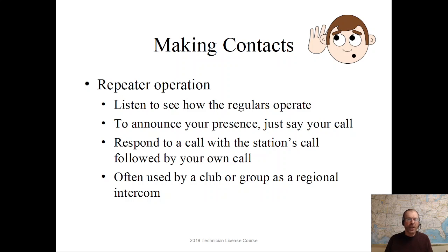Of course, if we intend to use the repeater right then and there, it's important to listen to see if it's in use already, because we don't want to barge in on somebody else's conversation. To announce your presence, just say your call. So, if I go on a repeater, I'm not going to call CQ. What I'm going to do is just get right out there and say, this is WA0TDA. Anyone around? And that's good enough to make a call for any other station that I want to hear on the repeater to give me a call back.